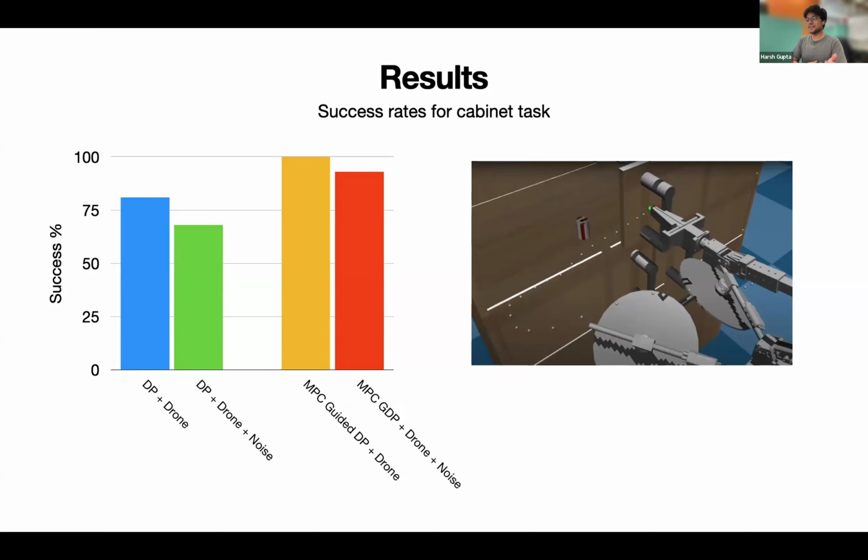But you can really see the benefits of guiding the diffusion policy with the MPC. In the first one, without noise, you are completely able to bridge the predictable momentum and constraints, but with noise, we still suffer some issues here, because of how unpredictable noise can be and the nature of diffusion policy, because we're generating, let's say, 0.7 seconds worth of actions at the instantaneous time step.